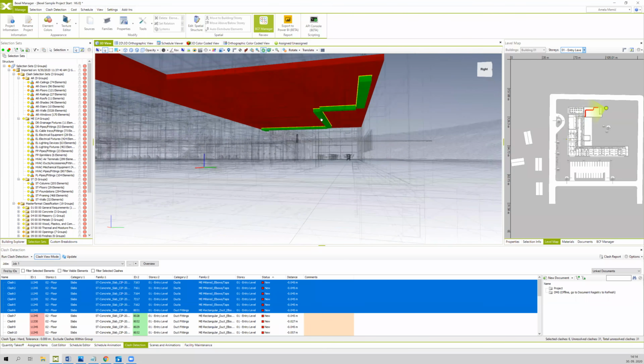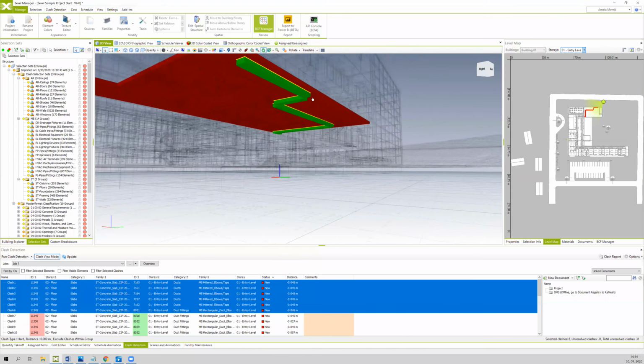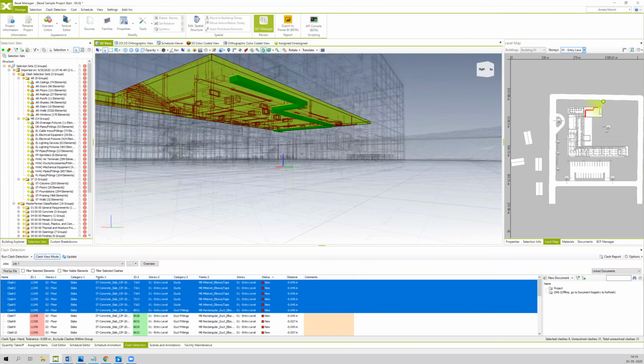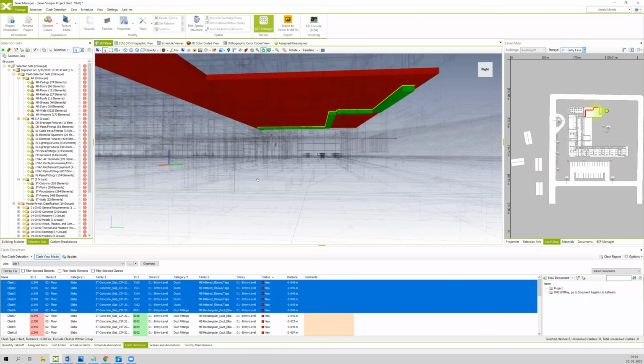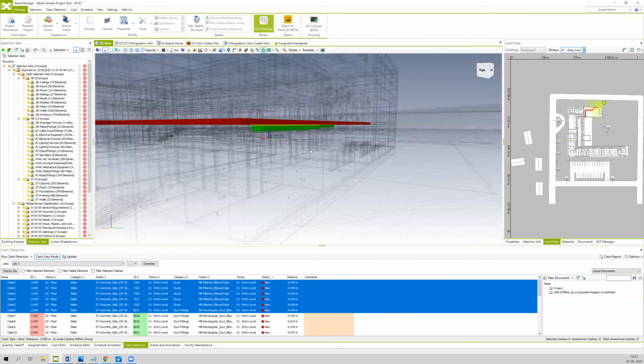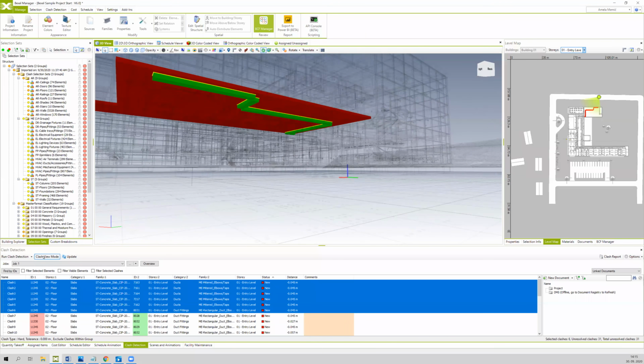As you can see, we have selected more clashes, and one group of elements is colored red and the other group is colored green. And also within the list, you can find information about every clash, which elements does it contain, on which floor it is located, and to which category and family those elements are actually a part of. So this is the clash view mode.